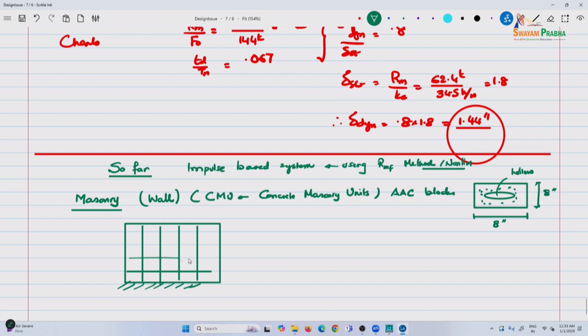We also say this is your wall. So you can have a reinforcement in this. So this is reinforced concrete masonry unit. The reinforcement will run through all the way, and you won't reinforce every unit of it. You might reinforce, so that's also the design part of it. So this is nominal 8 inches, this is 8 inches, and the reinforcement is running through maybe every third, every fourth, whatever the case may be.